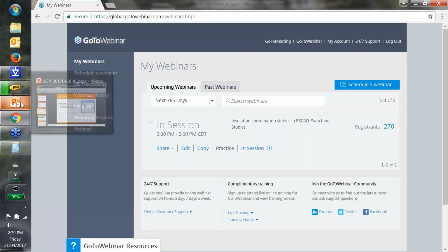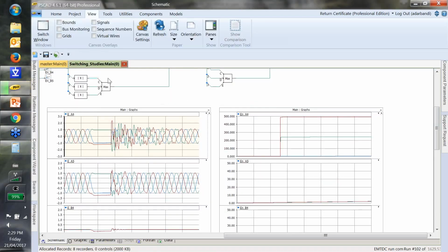And if you look at the voltage, it is about 2.2 per unit at a 380 kV system. We are looking at the SIL of 1300, which is way below the SIL of the equipment. So that means for this scenario, there is no violation.